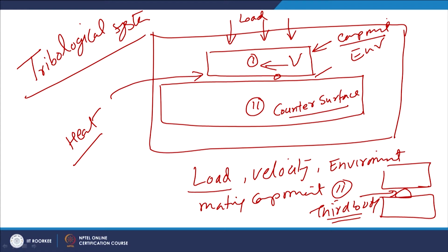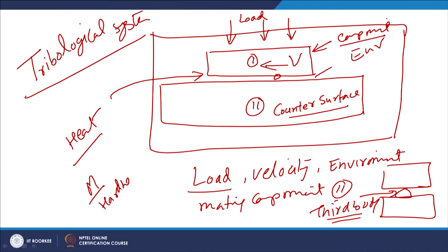Normally, both are not made of the same type of material with the same crystal structure, properties and hardness; it is always preferred that the two are different with regard to materials and hardness. This plays an important role in controlling wear and having a very reduced rate of wear. This as a whole is termed the tribological system.